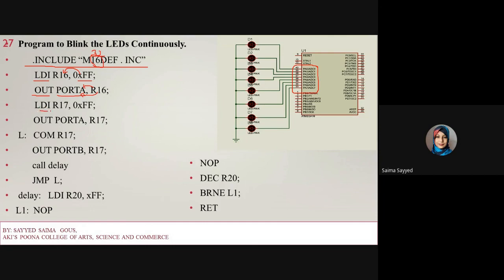Next, LDI R17, 0xFF. Now here again, OUT PORTA, R17. That means port A will become 0xFF. Now all LEDs will be on. All LEDs will glow. Next we have to complement it.